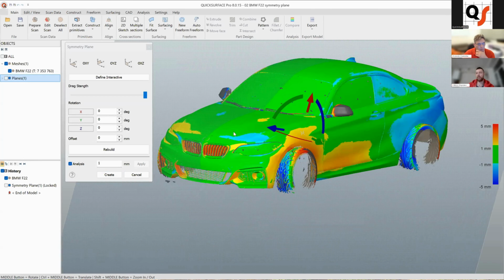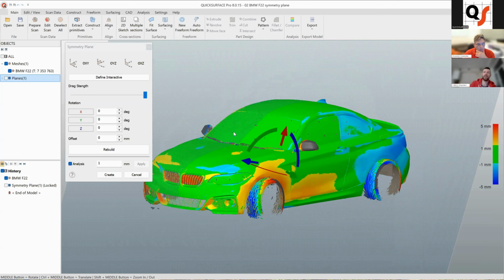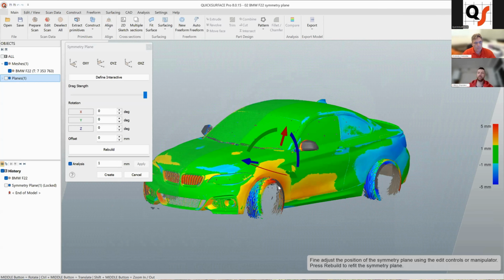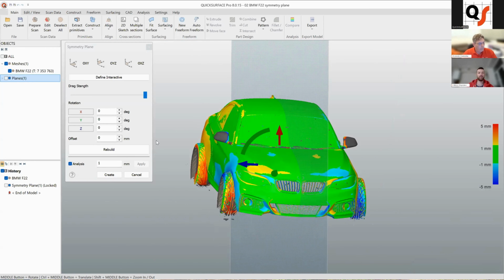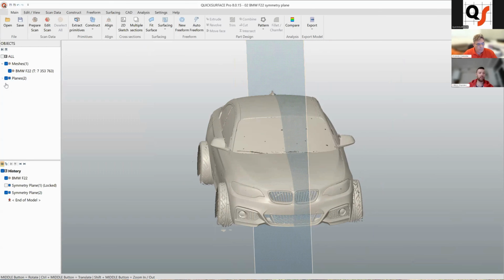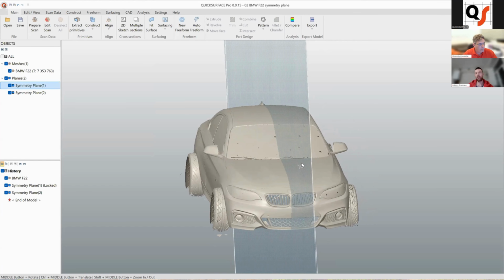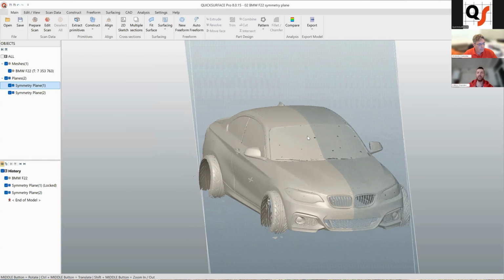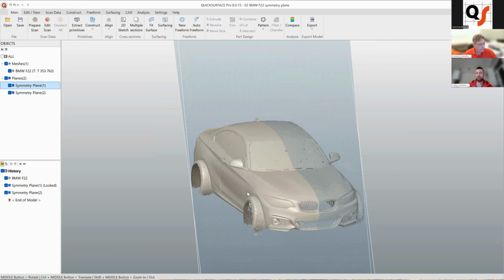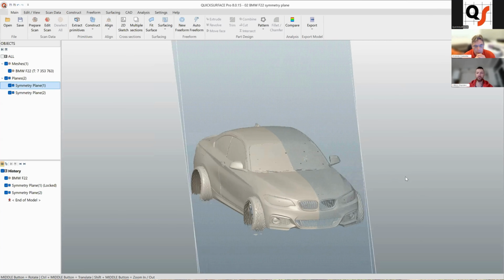See analysis here. So you can see how different results can be if you're selecting some different portions of your scan data. That means you can never know how perfect your car is, and you have to understand that if you want to work on some exact places and they have to be symmetrical for your designs, just use these options and create your object or reverse engineering parts based on different symmetry planes in different locations of these chassis.